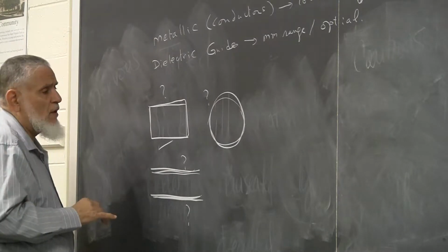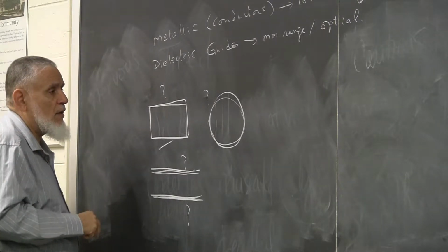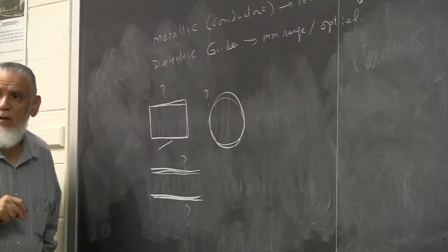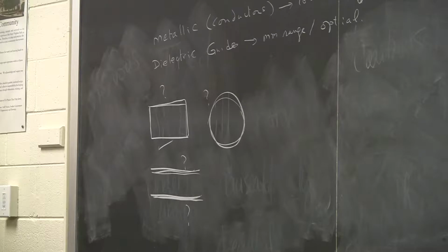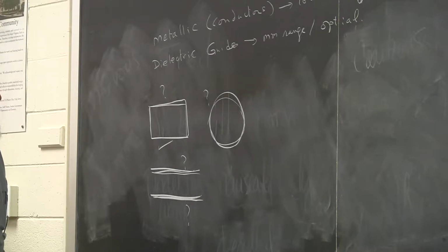Assuming obviously the conductor is thick enough, it doesn't matter beyond that, because you have a certain thickness for the skin depth that the signal will penetrate through, but if this is thick enough and you go beyond multiples of skin depth, you are in good shape.